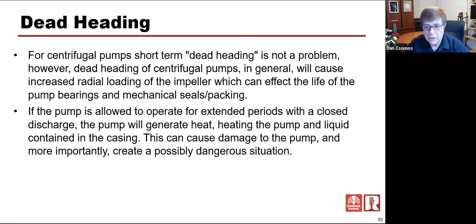One of the things I said was a pretty accurate test, within reason, is the deadhead test. Again, the curve is unreliable at that point, but it's going to give you an approximation. A deadhead test is about the only place on a curve where you know what you're operating at, which is zero flow. If you do a deadhead test and a pressure test there, and those two things are in alignment, then you know that pump is fairly healthy itself.